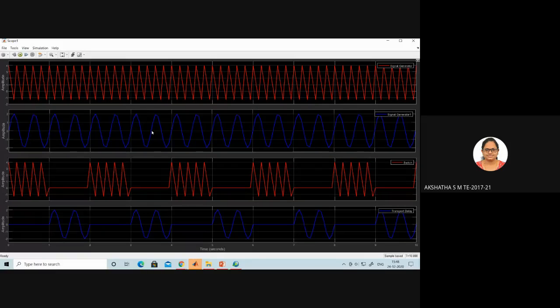Even in the scope you have to make a proper alignment. See here, exactly it is displaying plus 2 volts and minus 2 volts, right? Magnitude. And a little bit of variation in this is not an issue. But the sawtooth, see, it is not going up to minus 4, right? Only plus 4, then minus 1 something. So it all depends on adjustment.